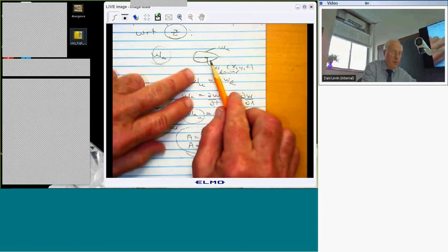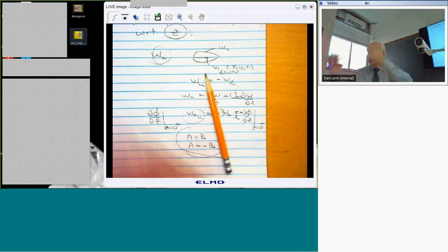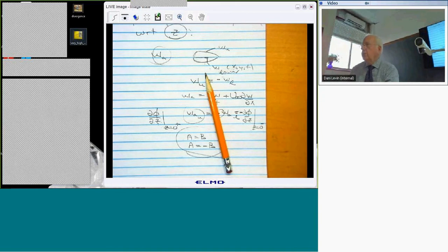This is fine, and if the upper and lower surfaces are both in phase, we can solve the problem without really treating the off-wing region, because d phi dz is 0 there, and when we do the integral, we just set those off-wing contributions to 0, and we're done. We just really have to integrate over the surface of the wing itself. But unfortunately, that's not the case when we are interested in having a net pressure.